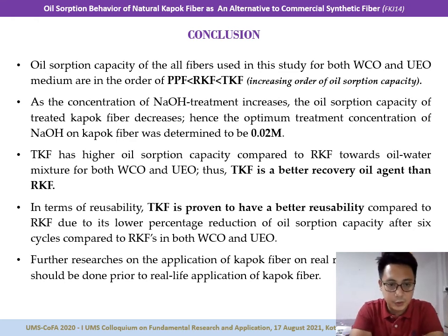In terms of reusability, the treated kapok fiber is proven to have better reusability compared to raw kapok fiber due to its lower percentage reduction of oil sorption capacity after 6 cycles in both waste cooking oil and used engine oil. Further research on the application of the kapok fiber on real river water samples should be done prior to real life application of the kapok fiber.